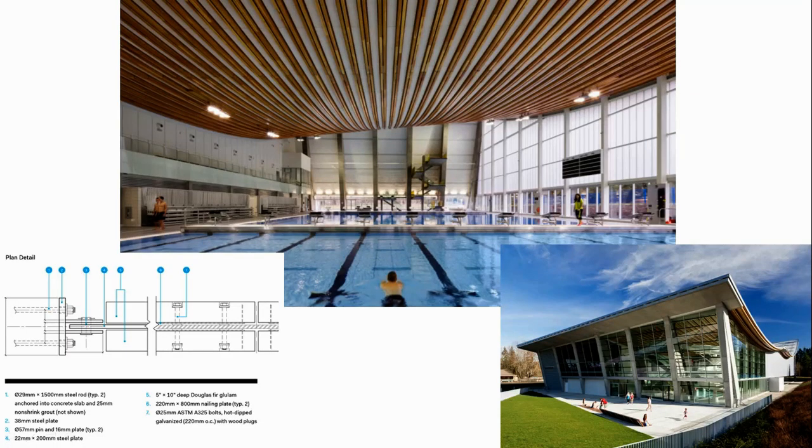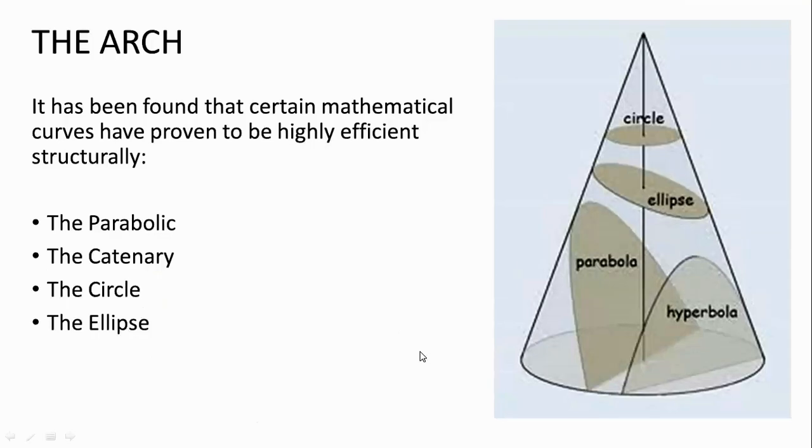And here's a lovely engineered timber version of the same relatively recent building. Again you can see here the concrete semi A-frame masts at one end, and this is engineered timber, a relatively lightweight series of glue laminated timber beams. You can just about see a detail here that are hung from one end to the other and flop naturally to take their shapes. So it's a lovely lightweight way of putting roofs together.